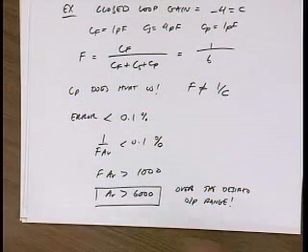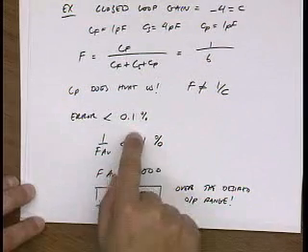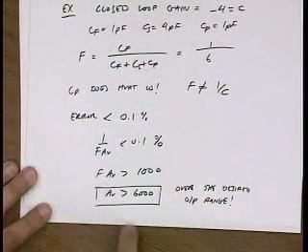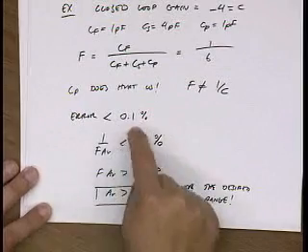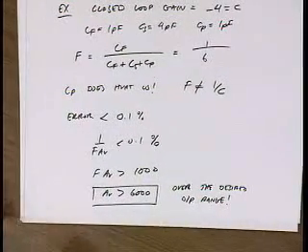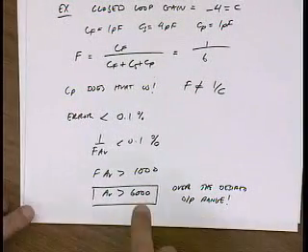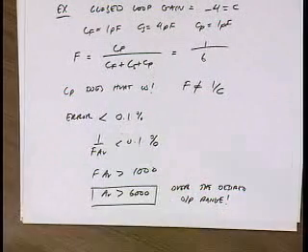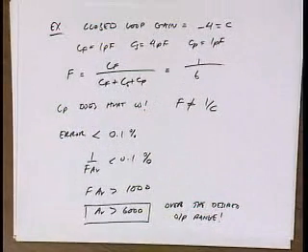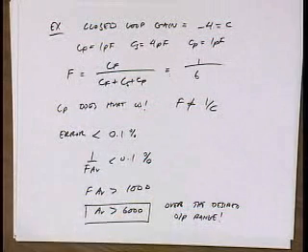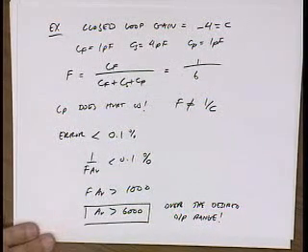Yeah, there are lots of other sources of error we haven't even started talking about, right? So if your total goal is 0.1%, you've got to split that error between all the various mechanisms that you know about. You have a budget, basically. And this is where the design decision comes from: how much of the error do you let go to your static error?